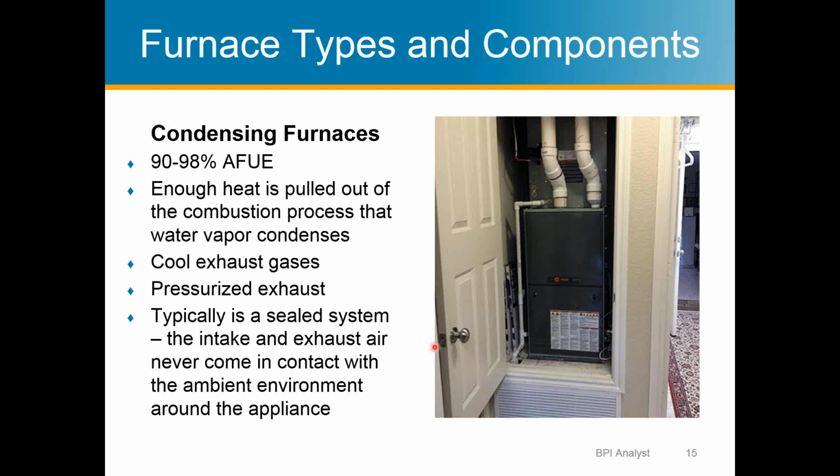So yeah, exhaust gases are cool. You still want them to vent all the way outside the building shell. The exhaust is pressurized here. So before, on any of the previous ones we talked about, the pressure inside the pipe was negative. So it was naturally drafting, just based off of the heat in the combustion gases. It was drafting up out.